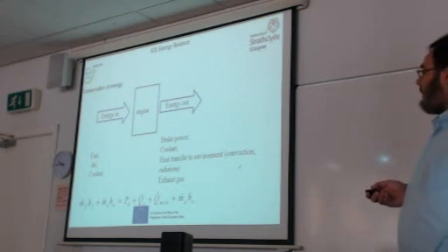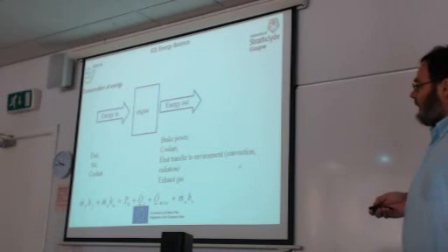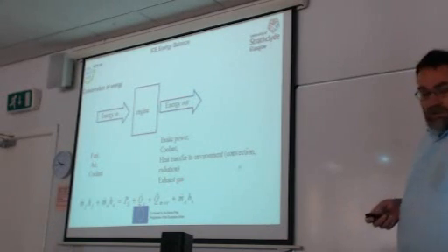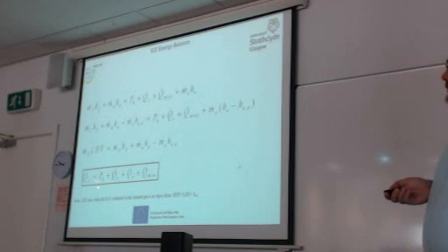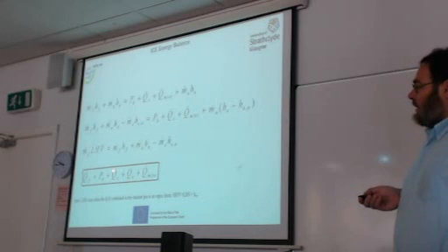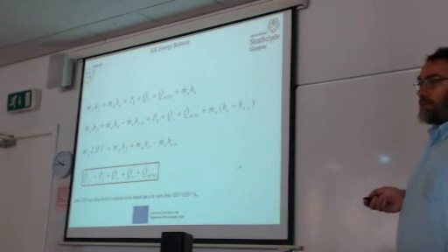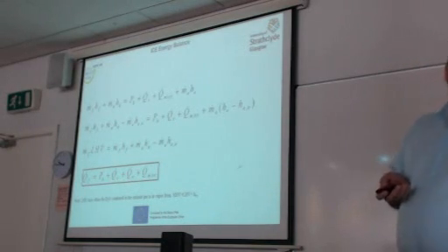We have a coolant needed for keeping the temperature of metallic parts at the normal level. We have a part of heat transferred to the environment, and also we have a part of energy transmitted to the ambient by the exhaust gas. So, in conclusion, the power provided by the fuel will be equal to the brake power of the engine, plus the coolant power, plus the exhaust gas power, plus the radiation power or miscellaneous power, which cannot be measured.